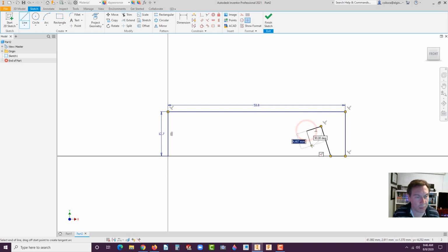Go ahead and drag this out, connect here. We'll make a small little jaw here. Click, and then bring this up about there. And again, you have freedom to do what you want here. I'm going to make the area where the finger is going to pull up on it. So I'm going to put this nice little angle right here. Click, and then there, click, and close that.